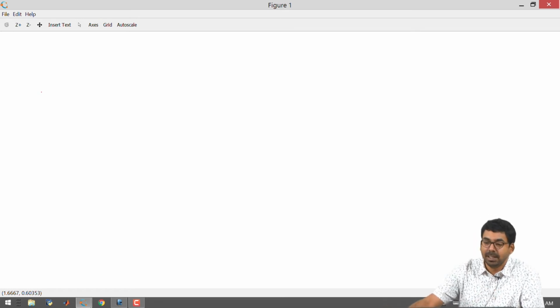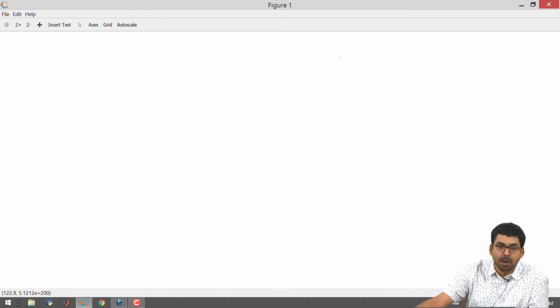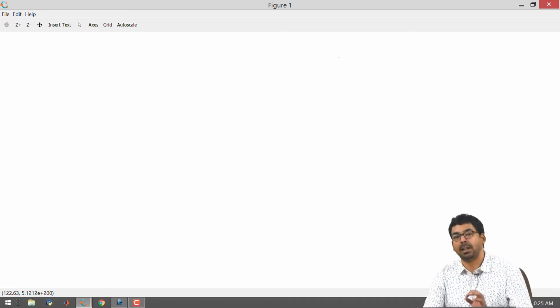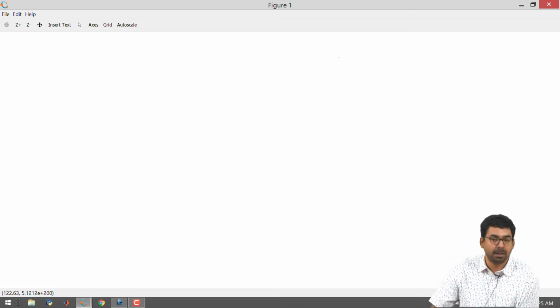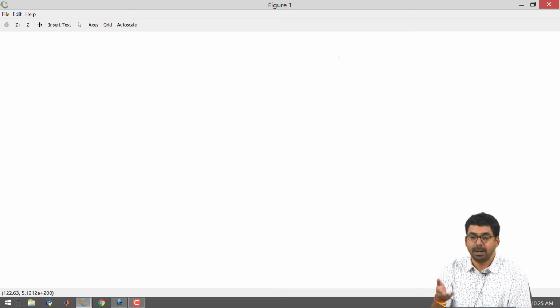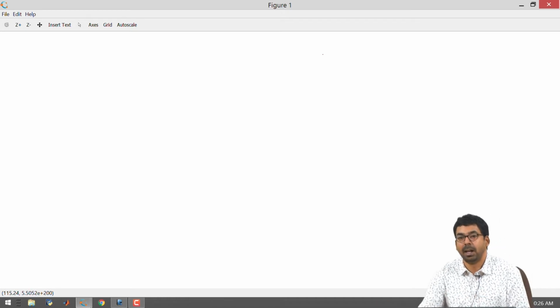Such kinds of things are known as instabilities in the way you have written the program, and the specific term commonly used in this field is the Courant stability criterion, commonly known as the Courant Friedrichs Lewy criterion or CFL. We will not go into the details about this stability, but one thing I wanted to make clear is that when you are writing these programs and manipulating them to see some of the things that we have seen in the theory, maybe you encounter a situation that your y axis blows up and you do not have a graph.